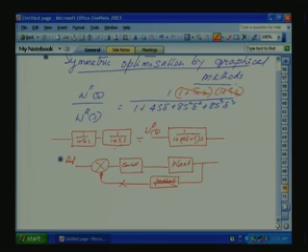Also, since the controller and plant have frequency dependent elements and the reference is also varying with frequency, the feedback signal should not have any phase shift. Even if the same gain comes here, if it gives a phase shift of minus 180 degrees, negative feedback becomes positive feedback. So, for the loop gain at unity gain, this phase difference should not be close to minus 180, it should be far away from 180 degrees. If we can do that, that is also another optimization.